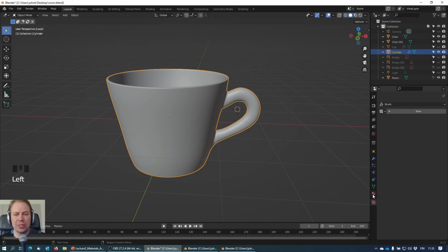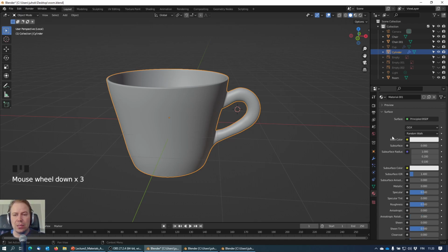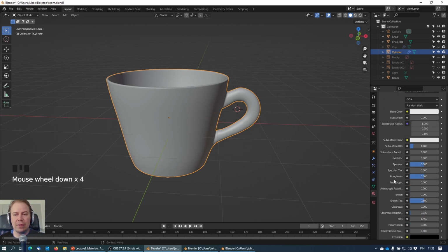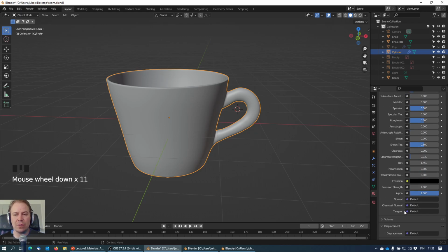So we don't have textures here because this new Blender is using node textures. So we have this principled BSDF that is a kind of umbrella term for all kinds of textures. Here you see a bunch of options that are going to be in nodes as well, and here you need to know that you have a transmission. In order to see the texture you're creating, you need these viewport options. So go to either material preview viewport or go to rendered.